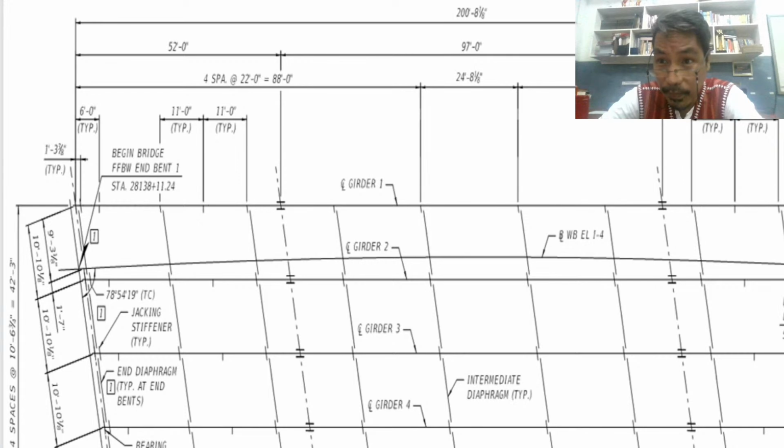So there is enough safety factor. There is enough safety factor for a 20 tons bridge. If that is specified as 20 tons, it can carry about 30 tons. But that is the critical point. If you try to do it up to 40 tons, obviously it cannot resist 40 tons. Maybe 30 tons can resist the load because of the safety factor. We know how we use the safety factor in ASD design. How much is the safety factor in ASD? 1.67, sometimes 2.